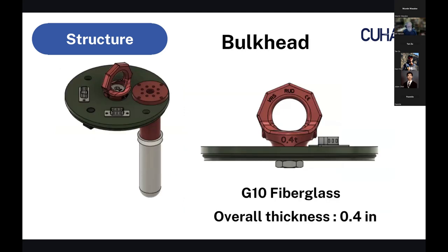Okay. Next is the avionics bulkhead. The avionics bulkhead is made by 0.2-inch thick G10 fiberglass plate assembled with screws. The maximum diameter is about 5 inches to fit the airframe, while the inner plate has a minimum diameter of approximately 4.6, attached with the cover for the section of the O-ring, and they're secured using stud and nut to prevent vibration. Each bulkhead has 2 D-subconnectors for the ejection system, and both bulkheads also hold the quad eco CO2 system and an eye bolt for chute attachment. Moreover, the top bulkhead also has the section to insert the cameras.